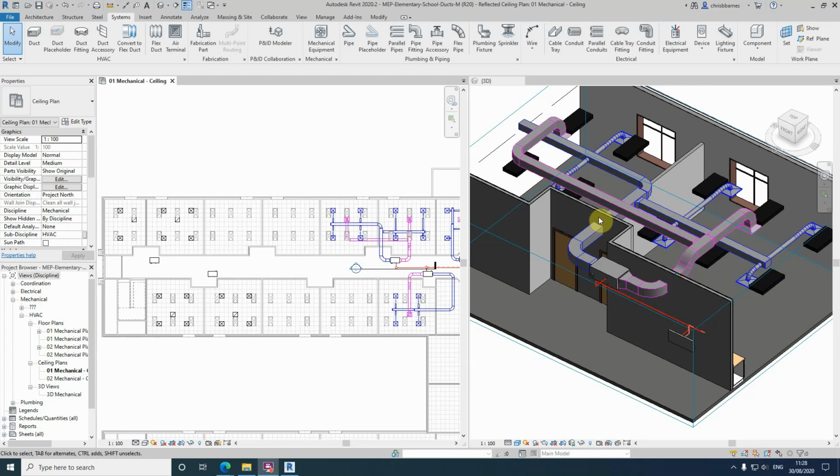To get the ducts and pipes at the right height, it is recommended that you start from the mechanical equipment, so in other words, start from this air handling unit. Fittings between changes of heights or sizes are automatically applied as you model the elements.